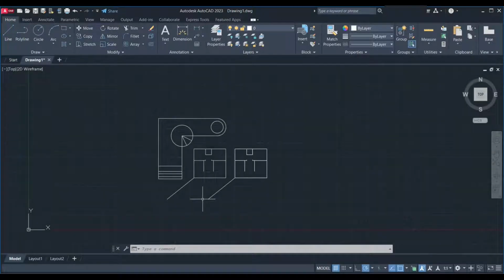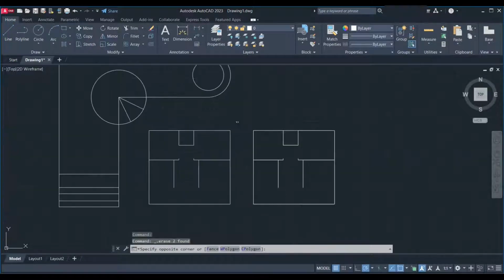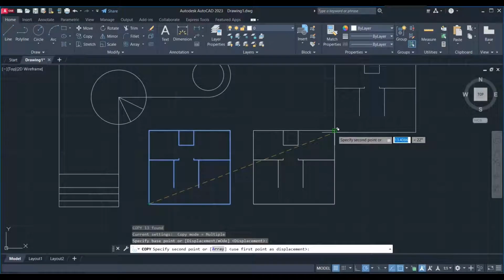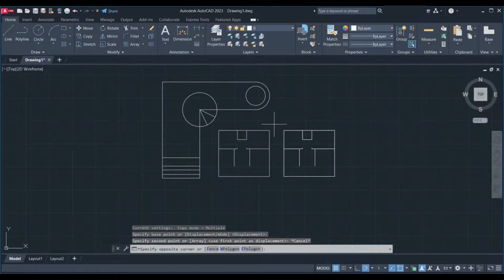My friends, please learn this well. Most of the time students get confused. An important point. For example, if you wanna copy this drawing and you want a specific point like this to be pasted to another specific point, do you see? For example, if you wanna paste here or here, in this case, you need to click on that specific point as a base point.